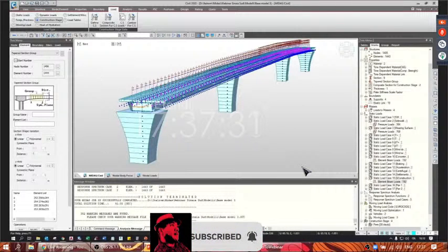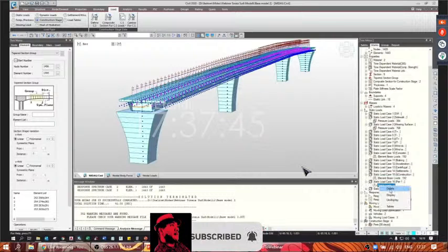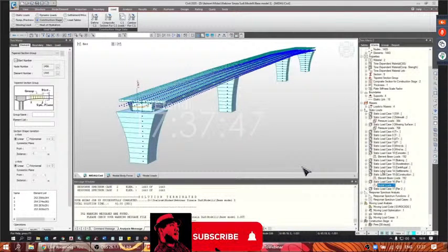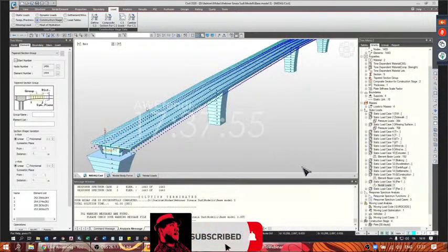between the two beams. Since the structure is a part of a bigger viaduct, the half lateral spans that we don't analyze are simulated with a nodal force. Okay, we can see here the load called pier. We applied it on a node located where the support is supposed to be, and the node is connected to the pier with an elastic rigid link.